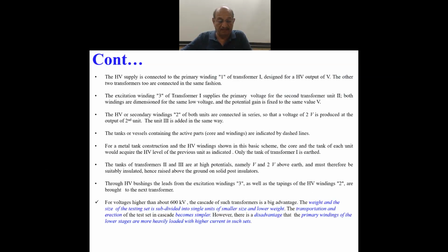I have covered every point written here. One more photograph we will see. For voltages higher than about 600 kV, the cascade of such transformers is a big advantage. The weight and the size of the testing set is subdivided into single units of smaller size and lower weight.